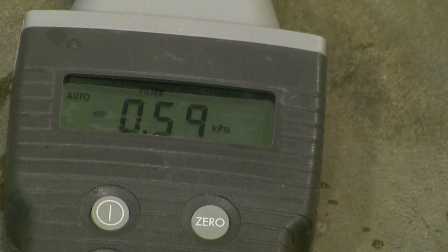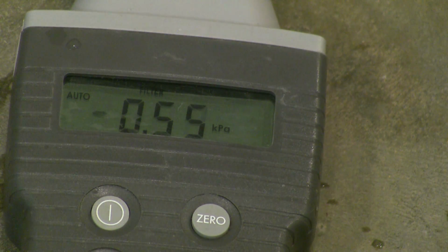And I suppose that tells us particularly that in the previous time we had bad data, the pressure difference from the previous run that I was writing down was in the order of 24, 25 kPa. Now that we've confirmed that it's cleared and have the filtering turned on, for the low flow rate, the 90-degree T is getting values in the 0.58, 0.51 range.